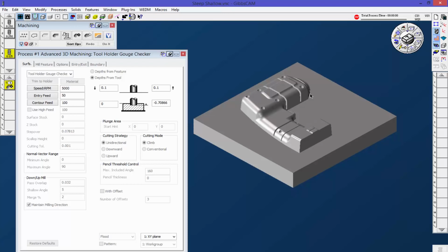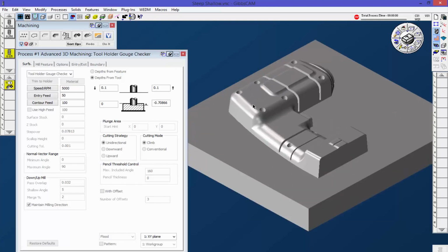Also, as you're coming down an arc like this, an end mill is cutting with that sharp corner, so you're really getting a good bite. It's cutting with the part that's supposed to be cutting. You don't have that horizontal push you get with a ball cutter, where everything gets pushed up into the Z as you're coming down. There's a bunch of reasons.